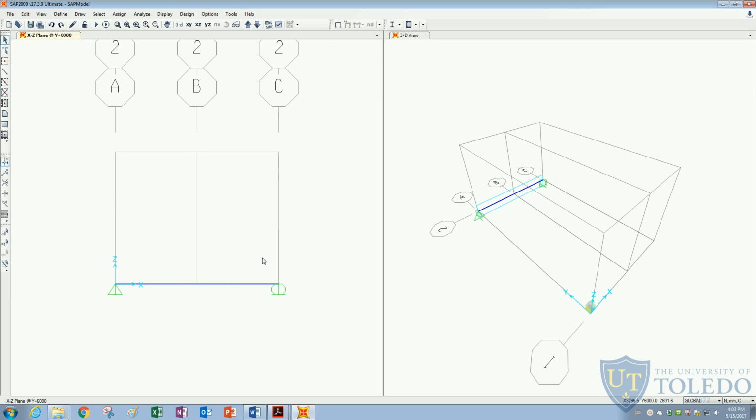and the center load, which will be the force. Alright, so now that we have our supports, we can start to talk about the hinges that we will use in this beam. The placement of the hinges is very important, and they should be located at the locations where their respective effects are critical. For example, a moment hinge should be placed close to where the moment in this beam will be maximum, and the same applies to the shear hinge.